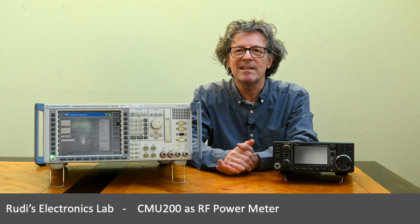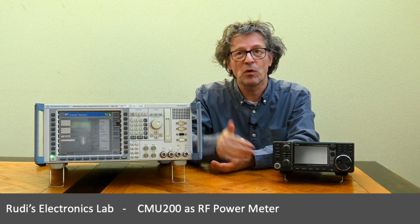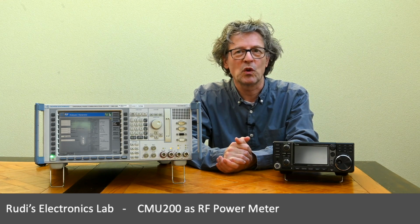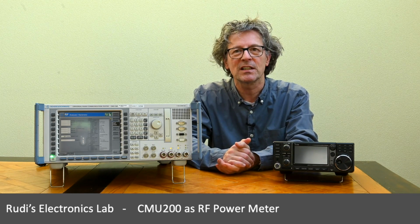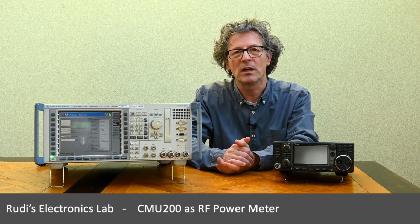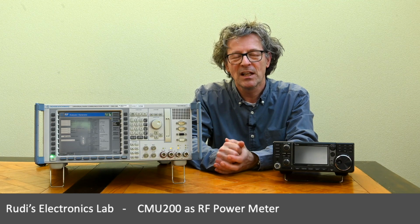And not only that, we got a real average measuring power meter that is really wideband. Over the whole wideband of the device is diode based. We also got a frequency selective power meter where we can select not only the frequency, of course, but also some of the filter cutoffs that are used there. And we can also investigate measured power versus time in a graph type of thing. So a lot of interesting things to be discovered here.